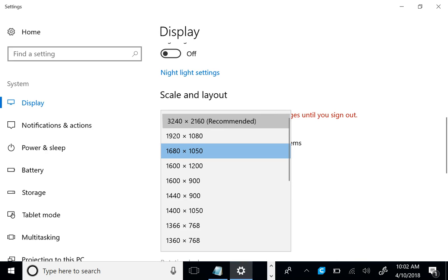And you can see, let me get rid of that raft. So that raft is under build plate. This thing here is to keep it stuck to the bed. So if I just turn that off, that whole thing should go away. I'll slice again. Okay, now you can see kind of what it's doing in there. Let me scale this up some more. Yeah, I scaled it way up so that I could play with the layers. It should be noted that you wouldn't want to print anything this big on the printer that it's using here.